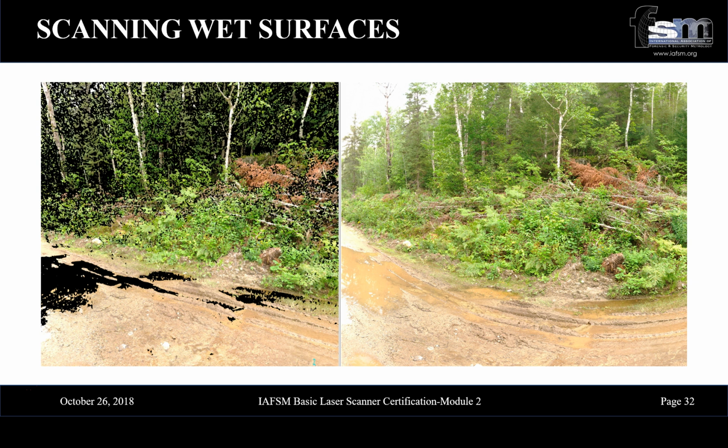The other thing that we just talked about was refraction. And so when we start having puddled water, even if we were able to scan through there, we have to take into consideration what the index of refraction is doing. So if we're trying to do something that is highly, highly precise, there may be some effect there. And I can't say that I've done enough to actually quantify this in any one scenario. But safe to say that it's probably a good idea to really consider your data if you're going to be using anything that's through glass or that goes through water.